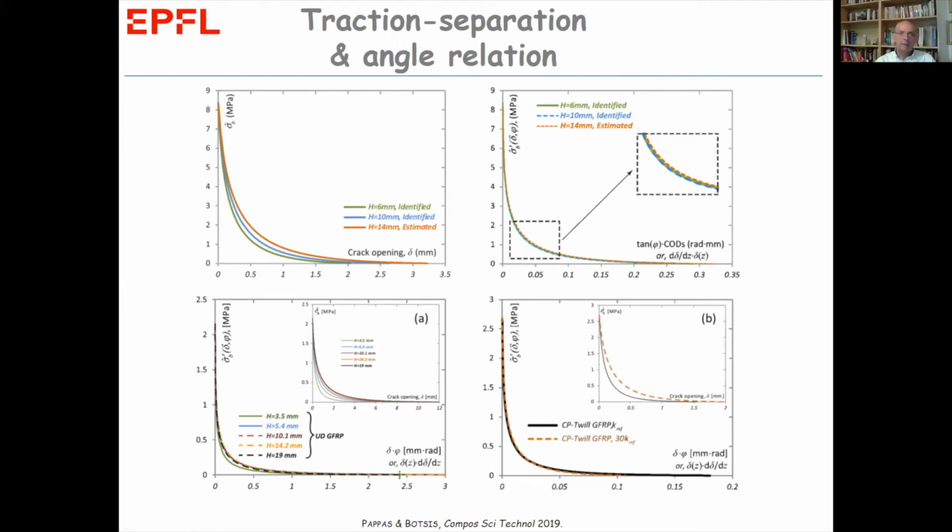So I take the crack opening angle and multiply by the corresponding crack opening delta, and establish this parameter zeta I showed you earlier, and replot the data. So I have here sigma as a function of delta and phi, plotted against the delta and the derivative of delta, which is shown here. Now, interestingly, the three sets of data collapsed to a single master curve for this system.